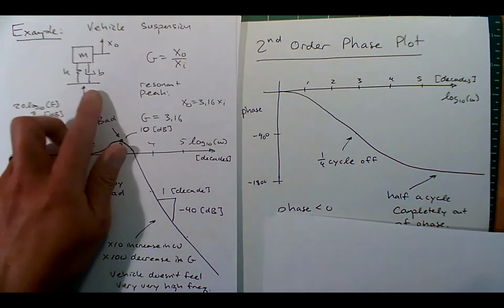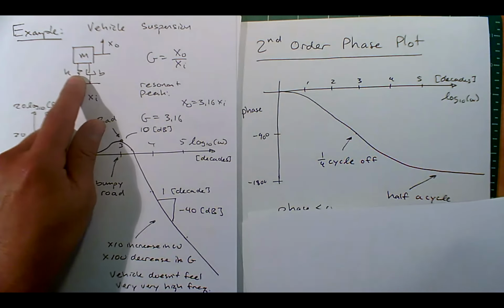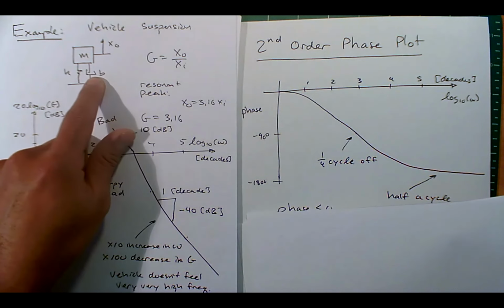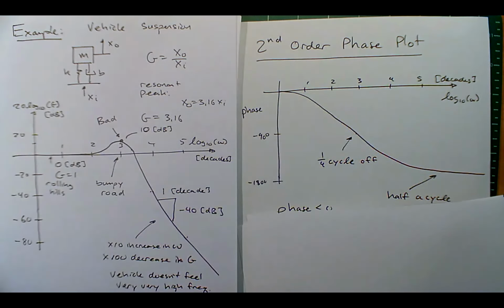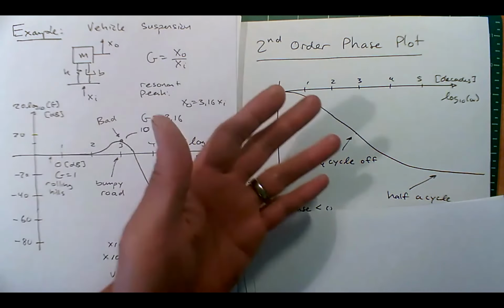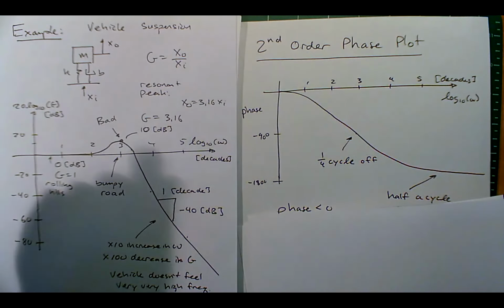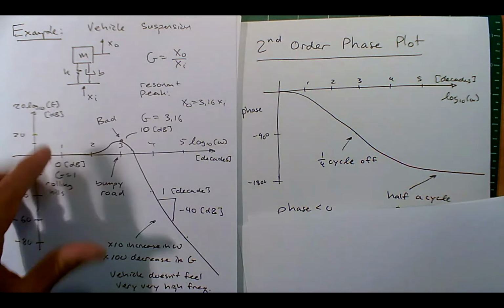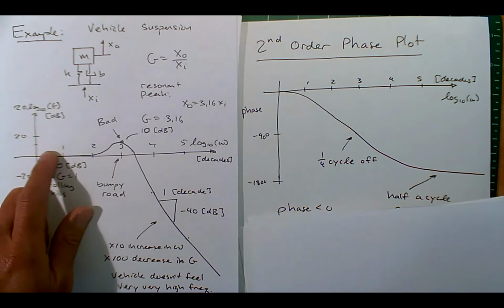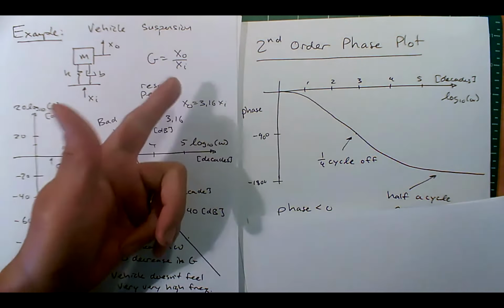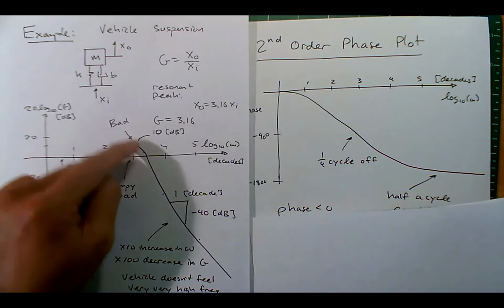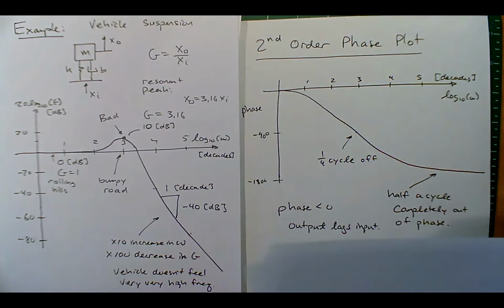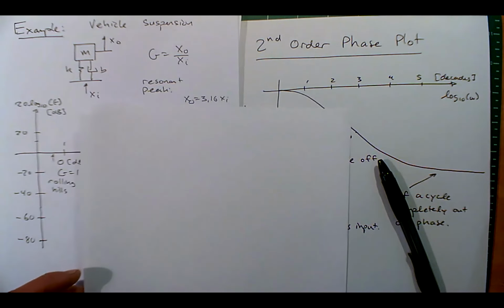Why do we call it second order? Because you have two elements. Remember, a K is like a capacitor, an M is like an inductor, and a B is like a resistor, okay? What we'll see in the simulation I'm about to show you is that I can build a similar system. It's the same math, guys, the same math, but I can use an inductor and a capacitor and a resistor all in the same circuit and get a second order response. I can get the same response. So it's kind of neat. So let's go back and finish it off with the simulation here.